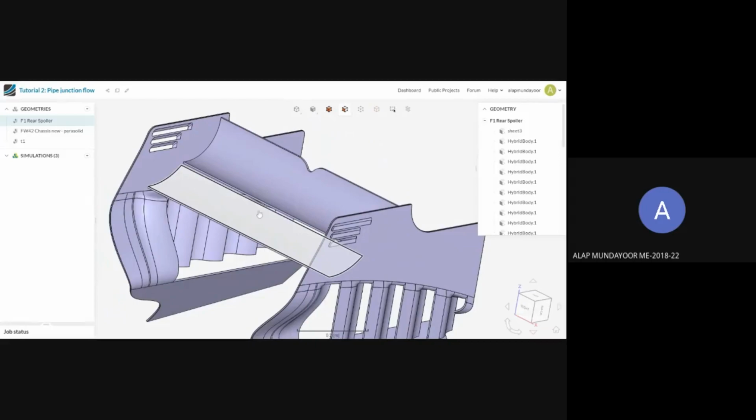When the driver actuates the button, the bottom flap undergoes actuation and lifts by around 50 mm, which creates a gap between the flaps, which allows a 15 miles per hour difference for the overtaking driver.